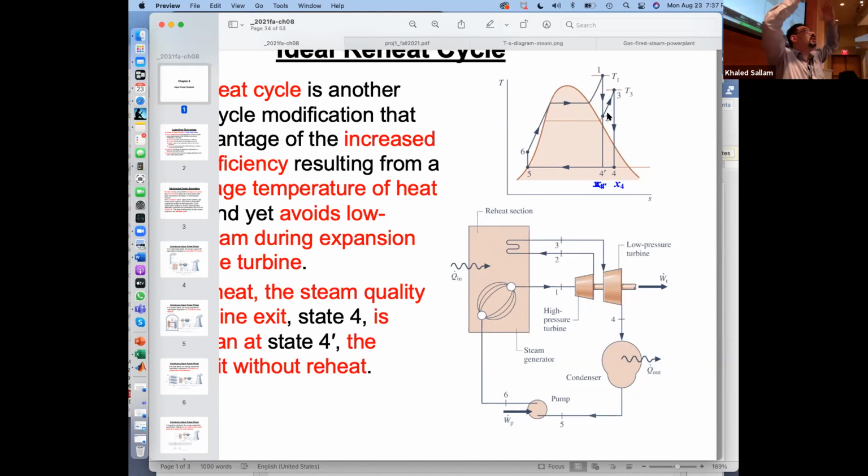Really, a 17-floor boiler with tiny pipes and steam trap and superheater, and all this has no pressure drop? Of course, it has pressure drop, right? But considering that the pressure is like 15 megapascal, what is the pressure drop in your pipeline, even if it's that long? That is something you can assess.